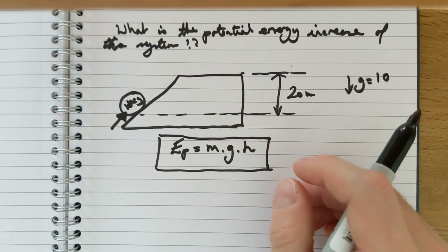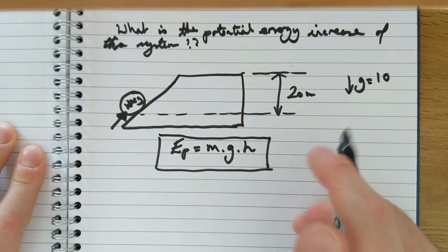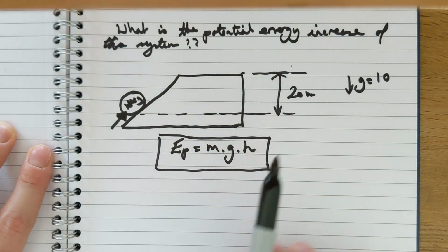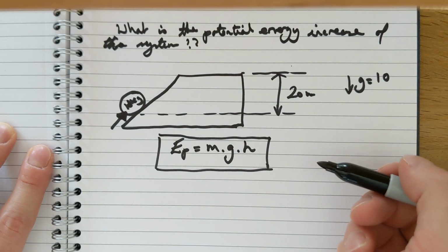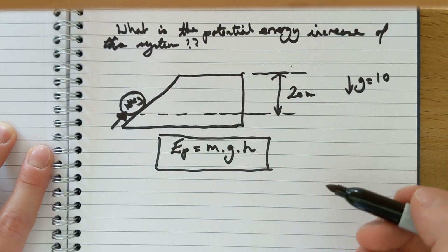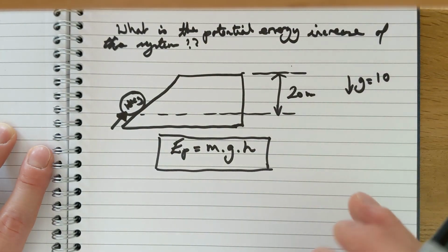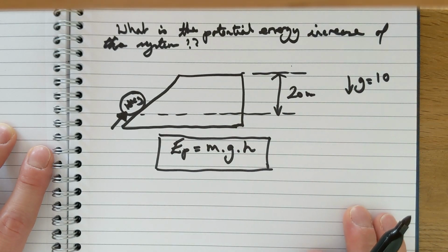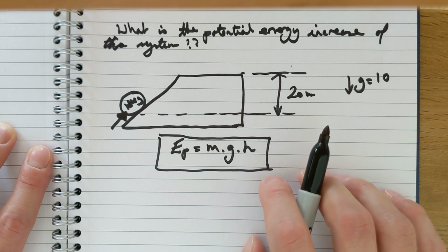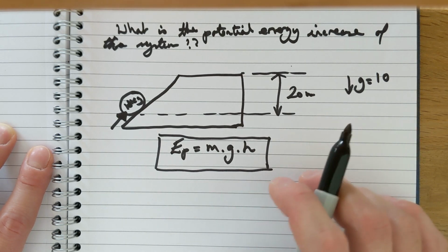And it's a very trivial example. You could very quickly and easily calculate it yourself just with the real values. But as an example for per unit, we're going to put all these values into per unit, perform the calculation, and then convert from per unit back to real values, and show that if you're performing calculations in per unit, you'll get exactly the same real values at the end as if you were to do it all with the real values.